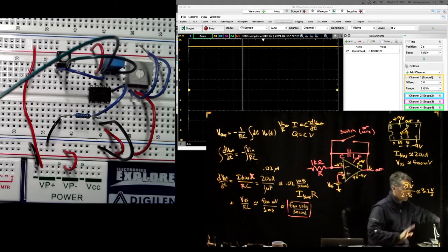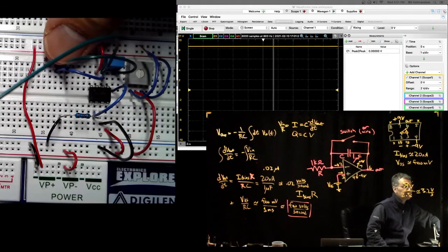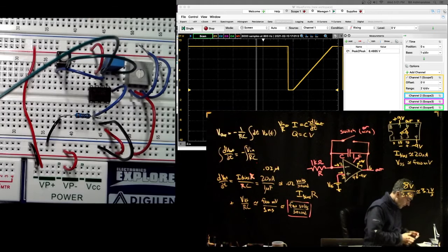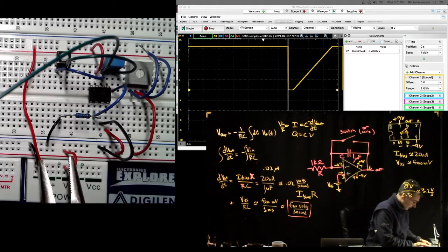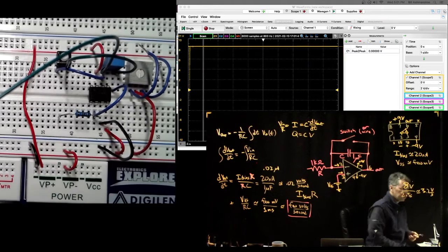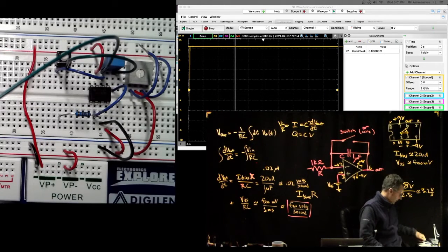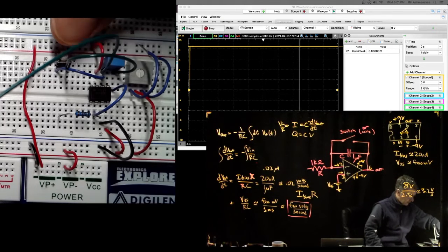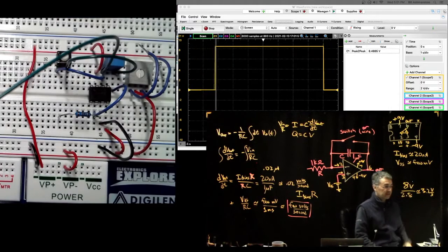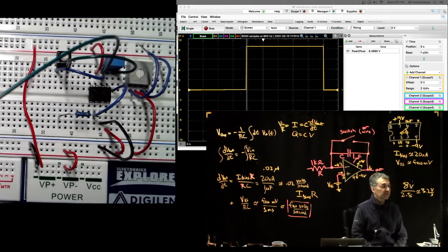So, okay, without changing anything yet, let me just reset the capacitor one more time, and you can see we're still at this few volts per second slope. And then let me reach in, and I will just remove the little grounding wire for this resistor. So now it's not connected to anything. The resistor is just floating in the air. And now let's zero the capacitor again. And I think we're going to see a much, much slower rise.